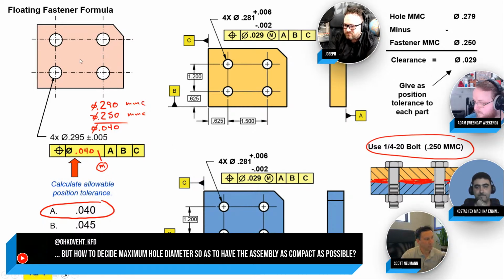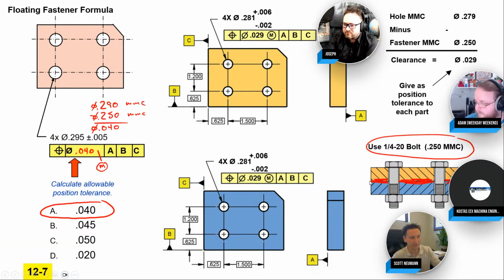And also you could have a problem with this pink shim, the hole gets too big and then the shim starts shifting in there and rattling around in there and sticking out the side of the plates, and that would be bad too. So that's kind of like another aspect of it, more of a stack up issue of just, I don't know, what can you handle? And that's going to be LMC minus LMC. So it'd be the biggest hole minus your smallest pin. That'll be a stack up rattling issue.